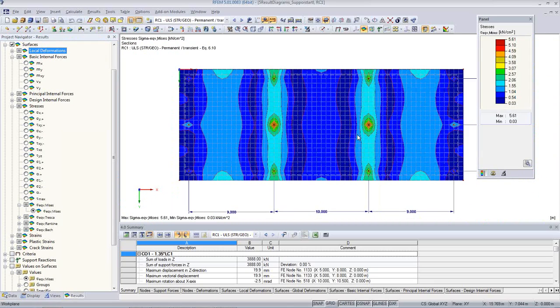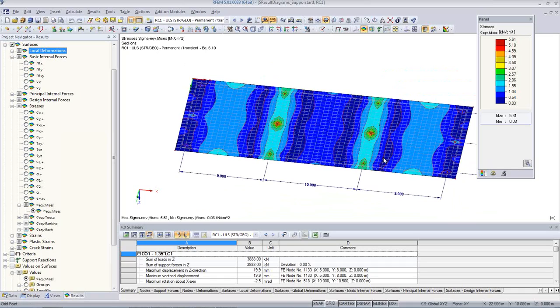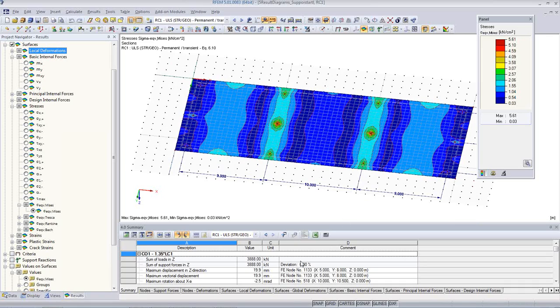So first of all, how to find singular points, how to find problematic points. Well, typically it's locations where there are high stress gradients. So if you make the mesh dense, you will get an infinitely high value, and it's very steep. You will have a very steep angle, the change from one finite element to the other one. I can show you this.